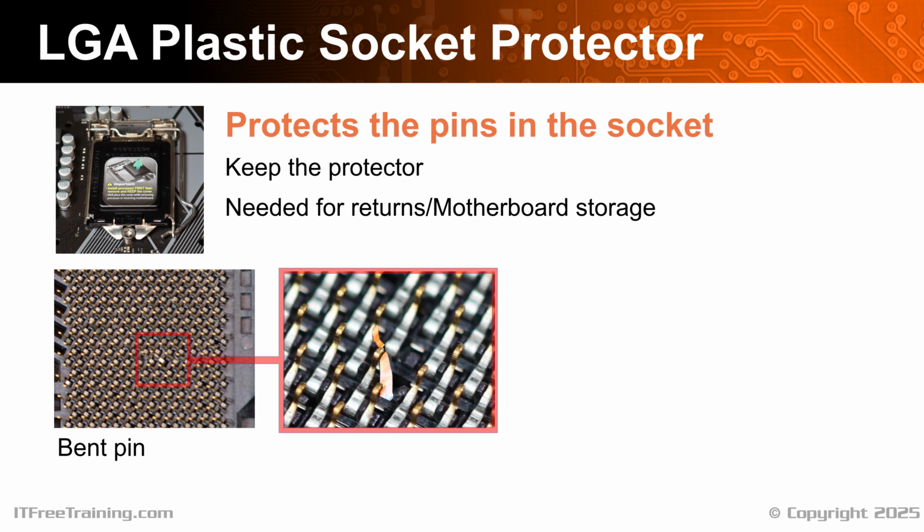In order to fix a pin like this one, you need a magnifying glass and a very steady hand to use a fine tool to push the pin back into place without bending any other pins out of place. This is a tricky process, and there's no guarantee of success. These pins are tiny, and even if they are a little bit out of place, they may not be able to connect to the contact points of the CPU.